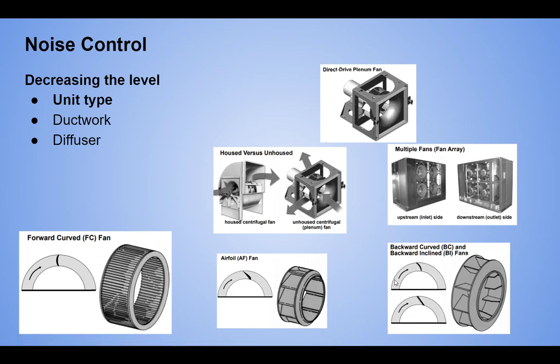A lot of times with efficient units, they're sacrificing on sound. Sometimes fan arrays are good, less static pressure. You're using less larger fans, but more of them. But this profile also is more of the upper end and not the lower end. Remember, the lower end's hard to control, anyways. So that's basically all we're looking at.